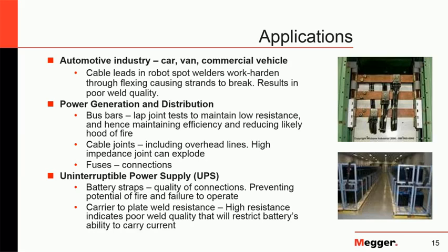So it's really, really important to prevent those conditions from happening, to be sure that we have a nice, healthy system, and that those connections are quality connections. The best and quickest way to assess that is measuring the resistance between the adjacent posts of battery terminals.